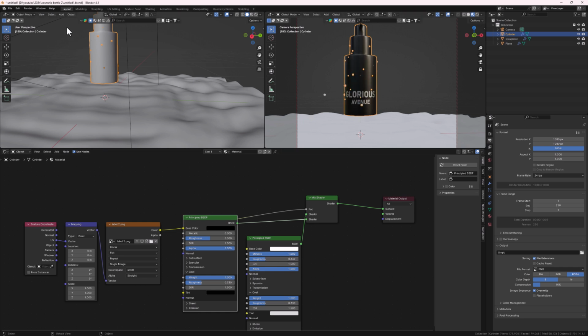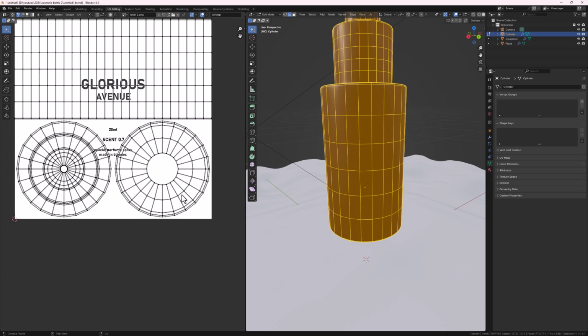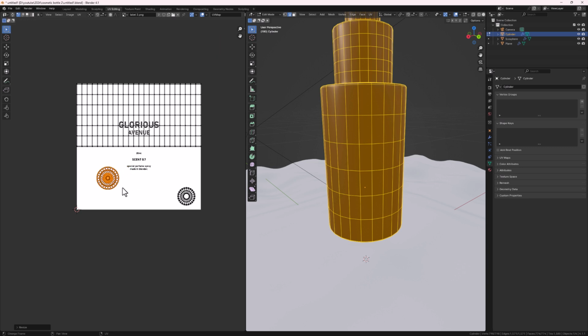Next, let's go into our UV unwrapping tab, and then let's position this properly into our scene. So I'll hit on UV, and then I'll select everything. Right? So first let's select one, hit on S to scale it down, then bring it down somewhere here. Select this one, S to scale it down, then bring it down to somewhere here, right?